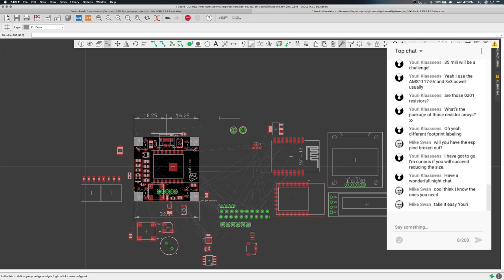And this would be, I guess it would be flush, you know. I should be able to fit one row on this side, one row on that side. I don't know if I'm able to route this board. That might be the problem. Put one on that side, and then you just solder those right angled connectors there. The ones that, you know, lay down. And you can use the female ones, and then the headers will line up with the edge of the board. Or you can use the male ones, and then your pin header, your DuPont connectors will maybe line up with the edge of the board when you plug them all in.